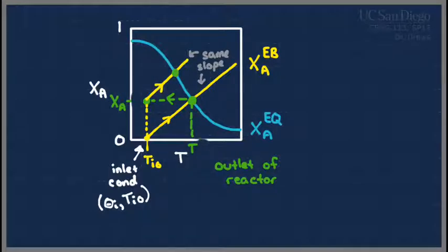The equation for the energy balance has not changed at all. The only difference is now the stuff coming in has a little bit of material reacted with it. So there's our second reactor. If we now go through the second heat exchanger, that's going to cool it down again and move our curve over this way. Remember, we've arbitrarily set it to cool down to the inlet temperature, so that point will be directly above the inlet temperature. And then we're going to react it again because we had a third reactor. So this line's going to come up in this particular direction, and now we're going to be here.